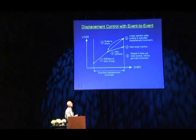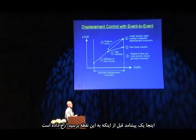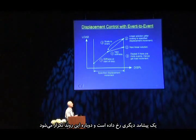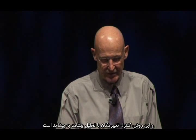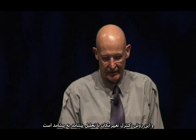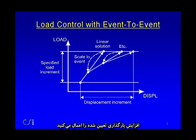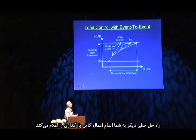Then you say, oops, we had an event occur here before we got to this point. So you have a second scaling, which brings you back to the event. Then you reform the stiffness, and you continue. And if necessary, if another event occurs in here, you just repeat the process all over again. So it's a displacement control with event to event. You can also use event to event with load control. And here it is with load control. You apply the specified load increment, linear solution, scale to the event, another linear solution with a different stiffness, scale to the event, another linear solution until you finish up applying the entire load.